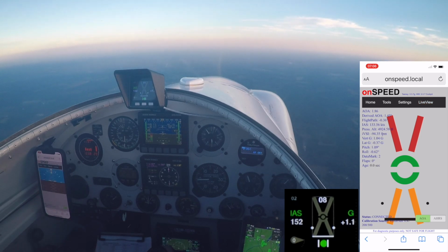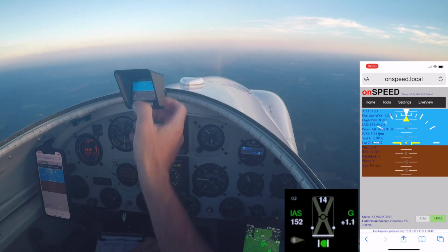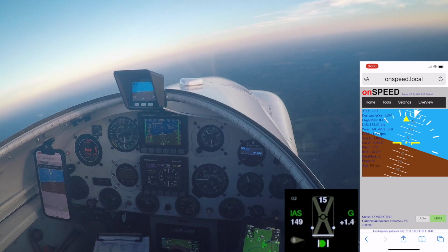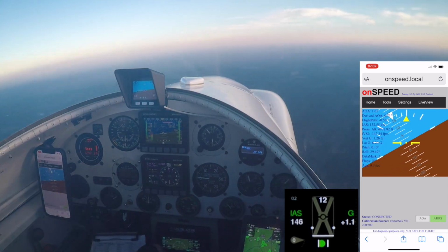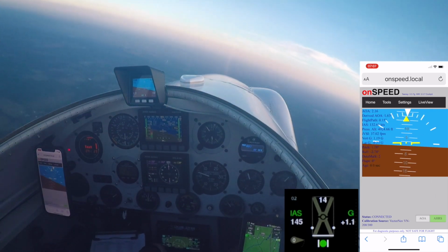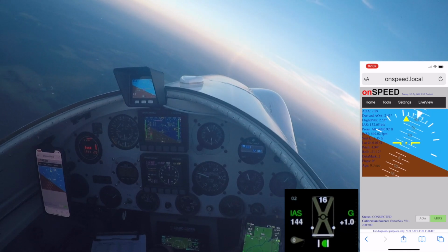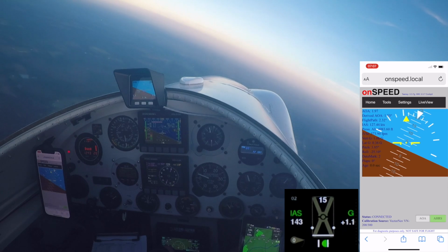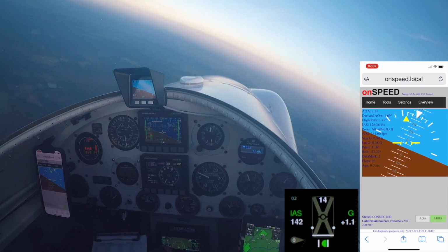What's nice about the AHRS page is it mirrors the AHRS up here. And notice it gives me a good warm fuzzy. I've got good IMU capability, which is going to be required if I'm using the internal IMU for our AOA calibration.